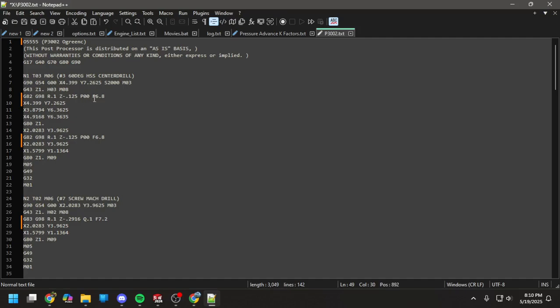The last thing you're going to want to do is verify that the post processor did not give you a weird dwell value, which it occasionally does. It'll specify dwell time of 1,000 seconds or 2,000 seconds. So if you've specified a dwell time of 0 in the drill operation parameters when you were doing CAM, it should come in as 0. The default is 1, which for some reason during the post processor translates to 1,000 seconds.